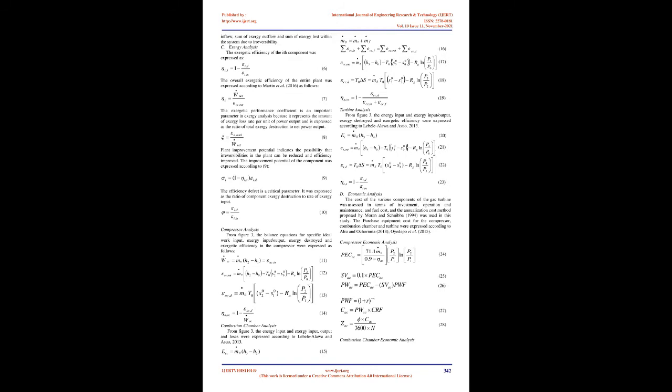Kwambe, 2005, examines the electricity generation process at a geothermal power plant in Kenya. The results show that the Olkaria I power plant has a 34.6% overall second law efficiency and a 15% overall first law efficiency. According to the analysis, 6 MW of exergy is lost in the separated brine, while 11 MW is lost in the steam transmission system. Turbines, condensers, and the gas system are all found to have significant losses.